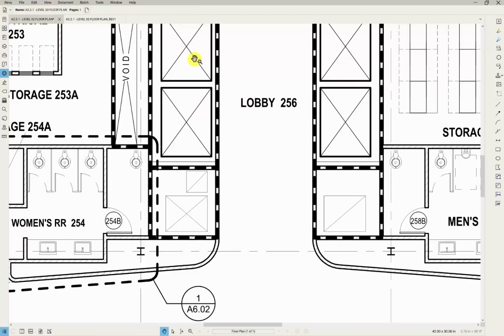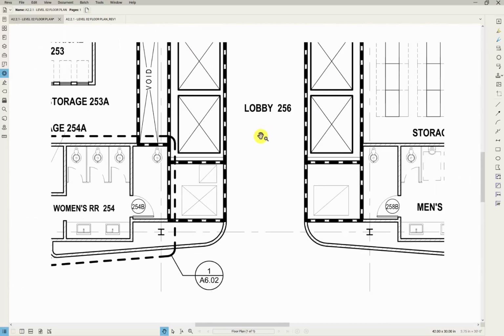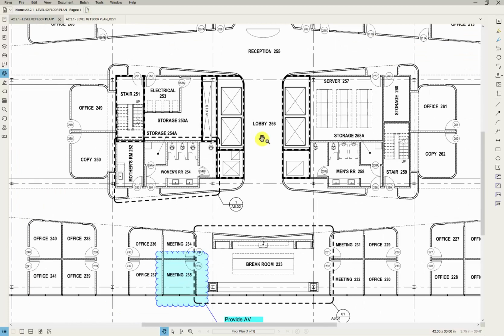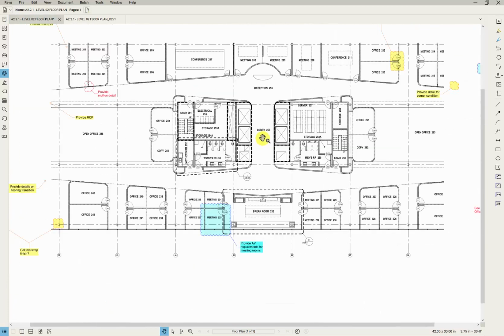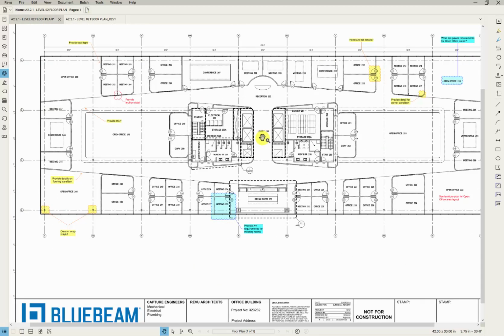All right, let's now go into something that's only in Bluebeam Revu Extreme. And the reason I'm showing you this is doing this hyperlinking is interesting. However, it's fairly time consuming if you're doing more than one or several. So what Bluebeam Revu Extreme allows us to use is batch link, which automatically creates navigational links with a specific group of PDFs based upon user-defined criteria.